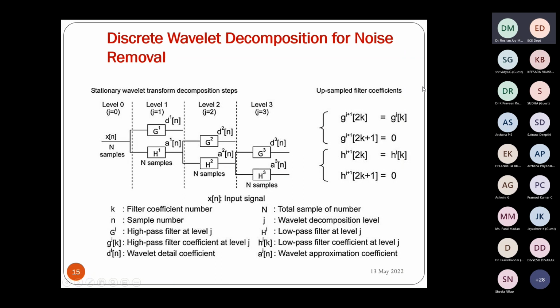Okay, so the simple way of denoising in Fourier: when the different bands required do not have common frequencies, we can go for the Fourier transform. What you can do is compute the Fourier transform of a signal, then find the bands in which you have only unwanted frequency components and no wanted frequency components. In that case, all the coefficients present in the transform in those bands you can make 0, and then you can compute the inverse Fourier transform and display that signal.